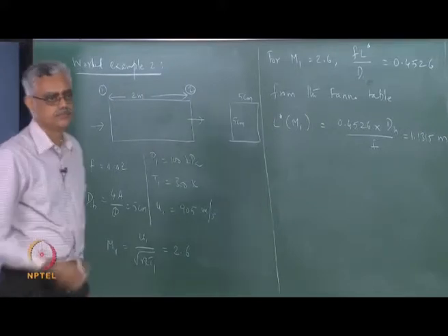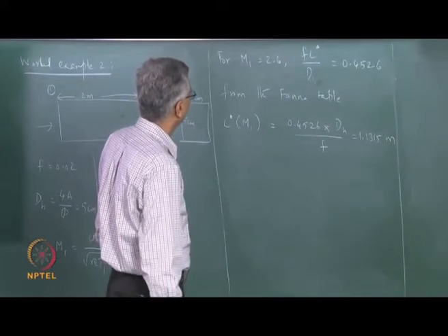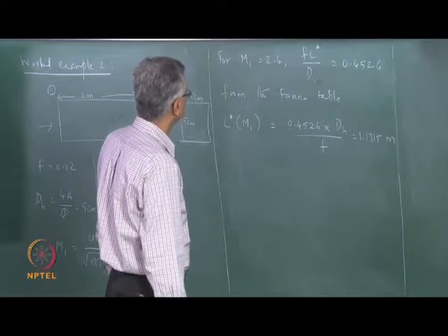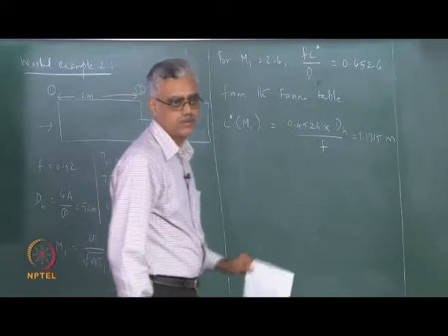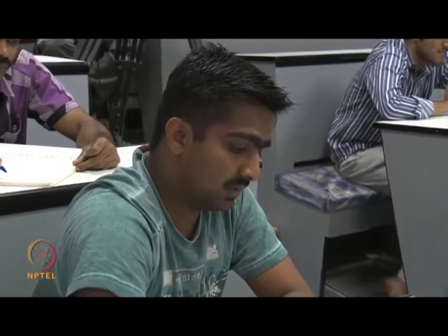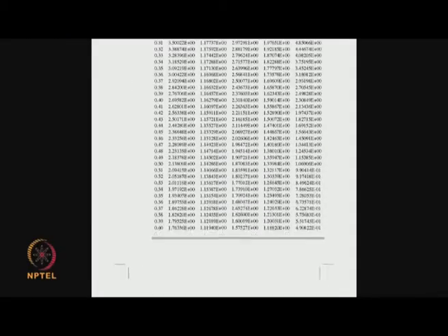Questions? So, that saying this gas table f L by D is 1.353. Please look in the supersonic. Yes, so the 2.6 Mach number, gamma equals 1.4. Yeah, 1.4. 1.353.